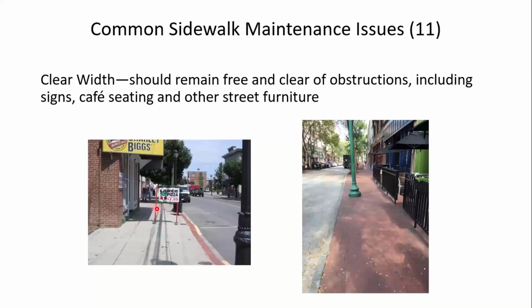The sign panel is above cane detection height, and so someone may run into that before they detect it with the cane. So maybe a little bit different sign design, and maybe move it closer to the street, so there's a clear, unobstructed path for the mobility impaired and the vision impaired.